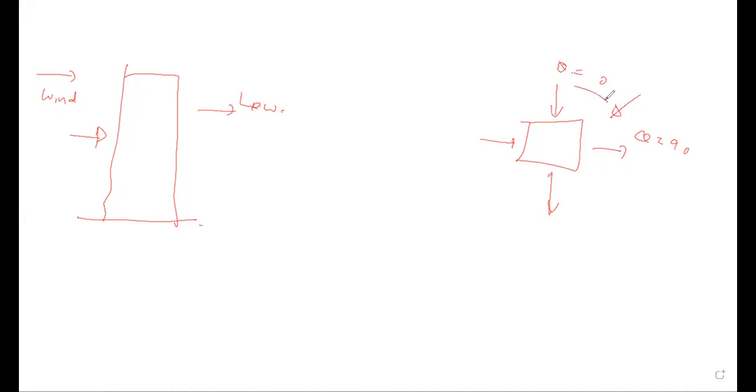For the moment we will use these. So this is the windward side, this is the leeward side. On the leeward side you will have suction, which pulls the building, and the windward side pushes the building. I had already calculated the wind load, so later we can calculate the wind load.